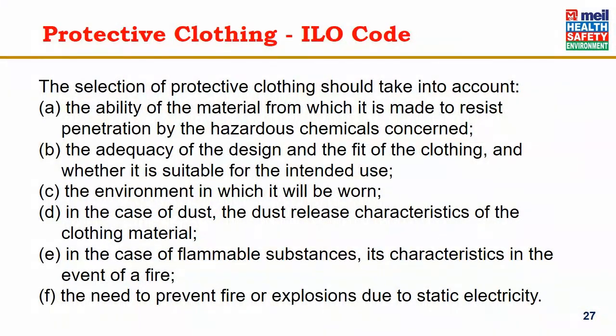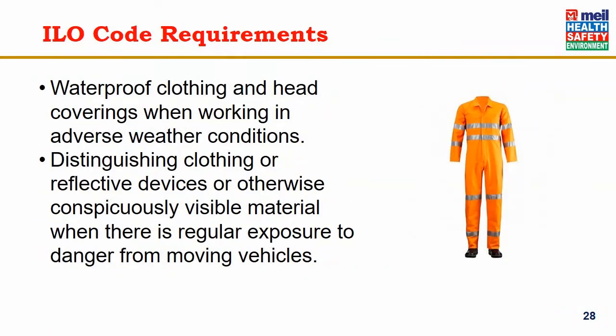D. In the case of dust, the dust release characteristics of the clothing material. E. In the case of flammable substances, its characteristics in the event of a fire. F. The need to prevent fire or explosions due to static electricity. Waterproof clothing and head coverings when working in adverse weather conditions is required. Distinguishing clothing or reflective devices or other conspicuously visible material when there is regular exposure to danger from moving vehicles.